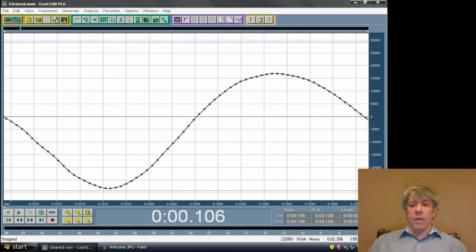So back to CDs and how they work. They had a left and a right channel, so there were two separate bit streams representing the right channel and the left channel, since it was stereo. And so the 44,100 hertz really was sort of a marketing thing, because actually it was 22,050 hertz for one channel, 22,050 hertz for the other. Now, of course, to sample both, technically the analog to digital converter probably went back and forth and sampled at a rate of 44.1 kilohertz, but that didn't mean the CD could actually reproduce 44.1 kilohertz unless you did some very special stuff, and that wasn't the norm.